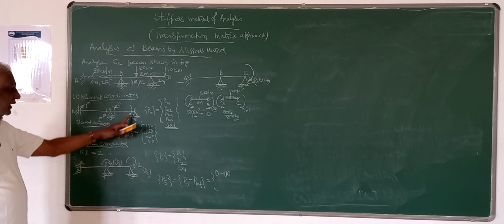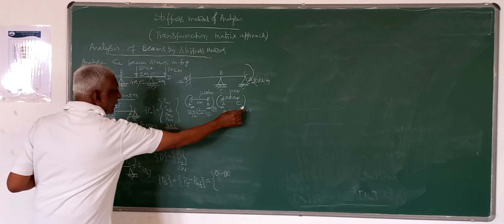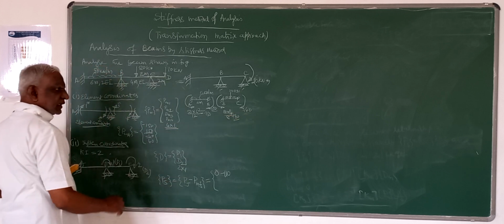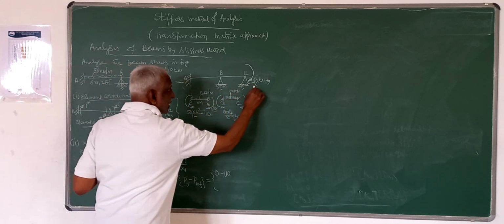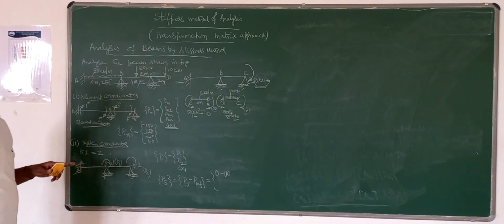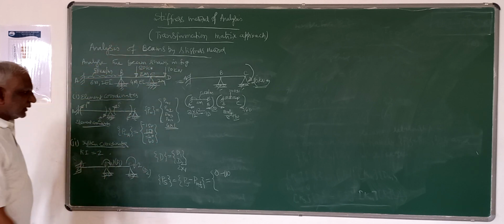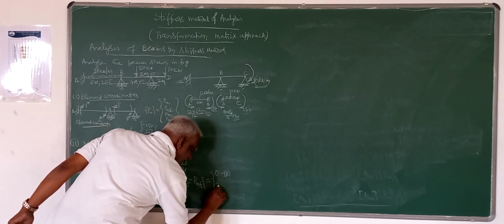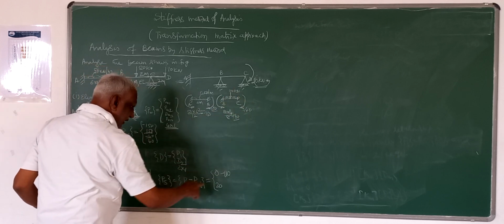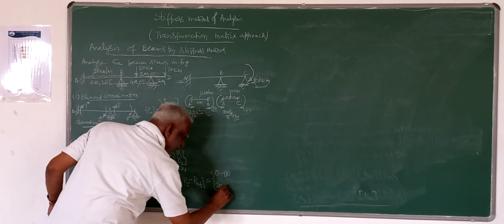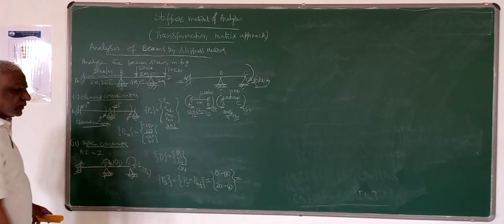Then corresponding to coordinate 2, that is at the joint C, only this load, that is plus 40, the member load. PMF is plus 40, but PJ is also there because this problem has an overhang. Because of that overhang, an external joint load is coming. So PJ will be 20 and PMF is plus 40, it is PJ minus PMF, so it is 20 minus 40, that is the load corresponding to 2.